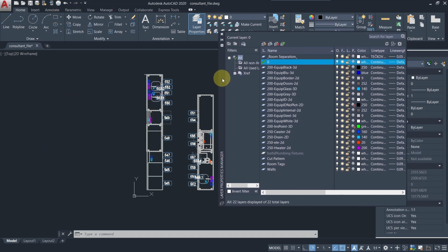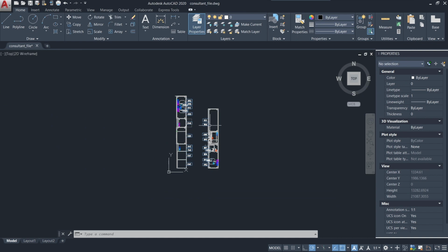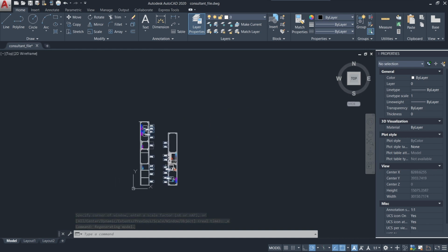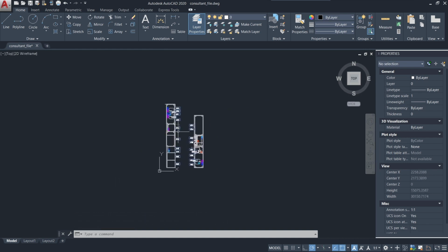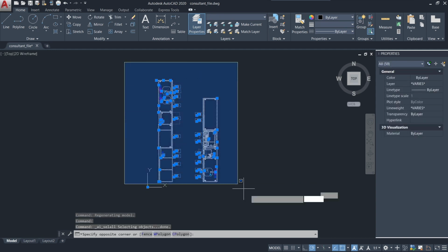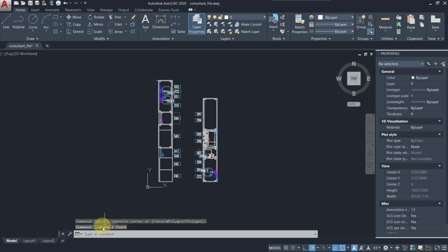First of all, I will move this away. We should delete all the geometry that we do not actually need for our reference. So in this example, I have a geometry that is really far away from anything else. This happens a lot of times in CAD files. So I will just select all with Control A, deselect the geometry that I want to leave, and just delete the geometry. You can see that I was able to erase 2 geometries found.